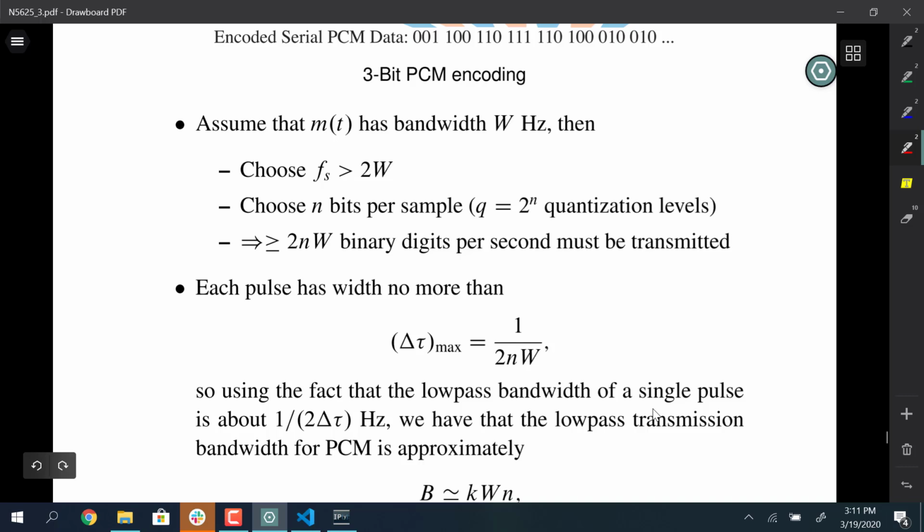If a signal has bandwidth W, then if we have Nyquist sampling theorem for low-pass signals involved, our sampling rate has to be greater than twice the highest frequency. I kind of did a demo of that to hopefully impress upon you that equal to twice is not necessarily the greatest. Greater than is the most practical scenario.